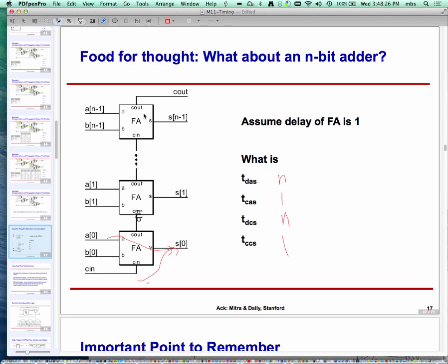Any further questions? Yeah. Maximum delay is not equivalent to propagation delay. Pardon? Maximum delay is not equal to the propagation delay. See, don't confuse the maximum and minimum, because maximum and minimum are referring to when a circuit has some variations because of temperature or because of manufacturing or something like that. Okay, so that's why they use the term contamination delay and propagation delay, because contamination is under current condition: what's the earliest time it can change and what's the latest time it will take to stabilize?